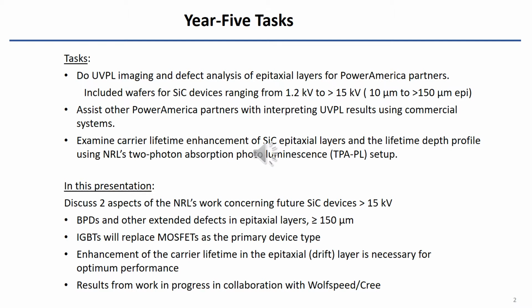In the future, IGBTs are going to replace MOSFETs as the primary device type. It's going to be a device that requires a long lifetime in the drift layer, and certainly IGBTs will need that for optimum performance. And we'll be reporting on the results of work that we're doing in collaboration to evaluate thick epitaxial layers and look at their lifetime throughout their whole thickness.